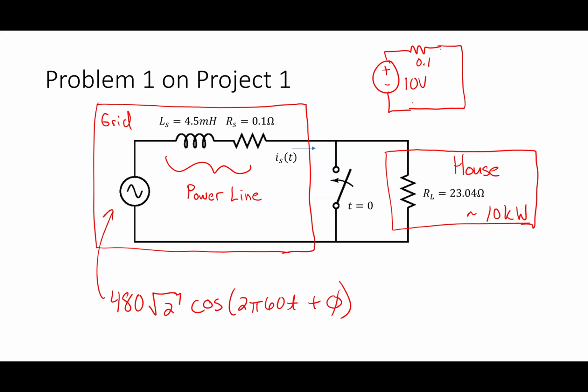If I have 10 volts and 0.1 ohms, how much current's going to flow? 100 amps, right? So if I had a 50 amp breaker, that breaker would be in series with that source, and it would open because it sees that the current exceeds 50 amps, so that the current stops flowing. So it protects, right? The job of it is protection.